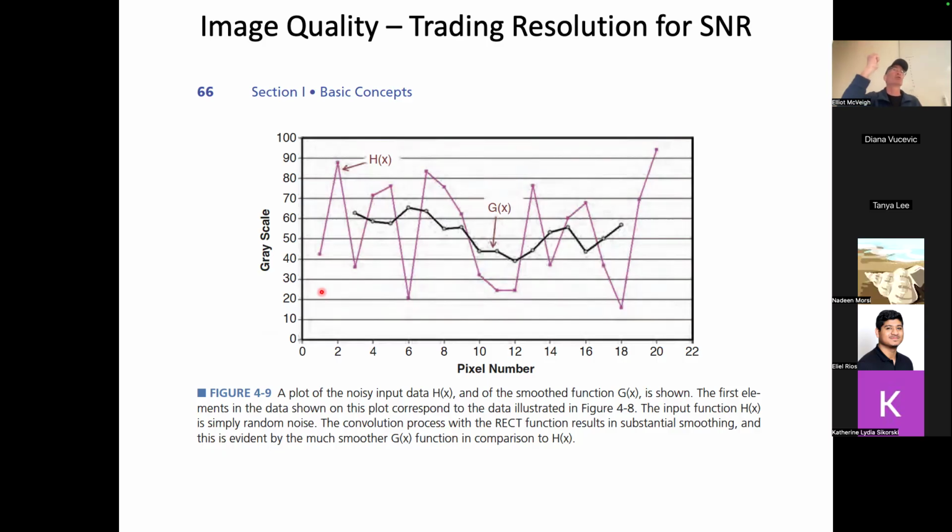You can imagine you could cool down that coil. Put it in liquid nitrogen, and the noise will go way down, because the motion slows down with temperature. It's called thermal noise. But the patient, you can't cool them down too much. They're at 98.6 Fahrenheit or 37 Celsius, and that is the noise you're going to see. That produces random signal on top of whatever signal you're trying to measure.